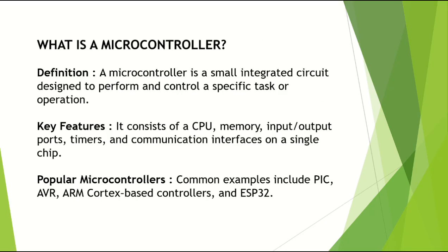What is a microcontroller? A microcontroller is a small integrated circuit designed to perform or control a specific task or operation. It consists of a CPU, memory, input-output ports, timers, and communication interfaces on a single chip. Popular microcontrollers, common examples, include PIC, AVR, ARM Cortex-based controllers, and ESP32.